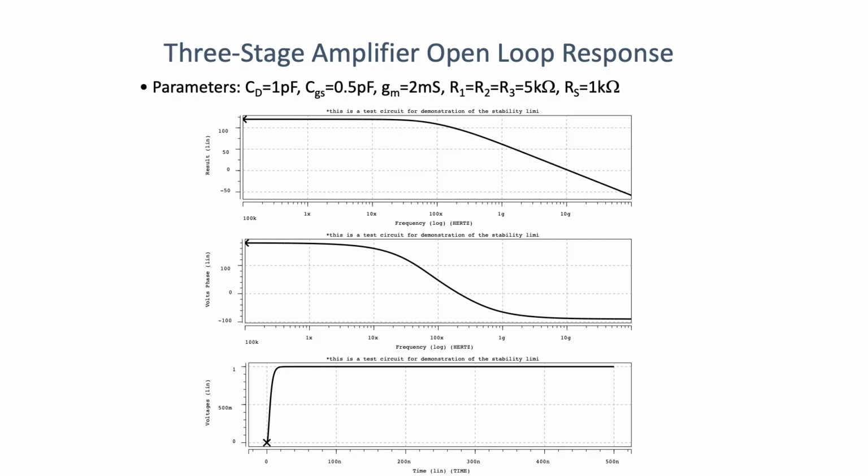And the Bode plot shows the same thing. The amplitude is at 120 at low frequency, and then the slope starts dipping first and then dips more. You basically have 3 left half plane poles. Nothing really exciting about this, it's very vanilla.